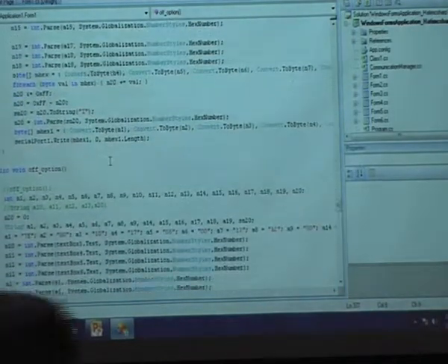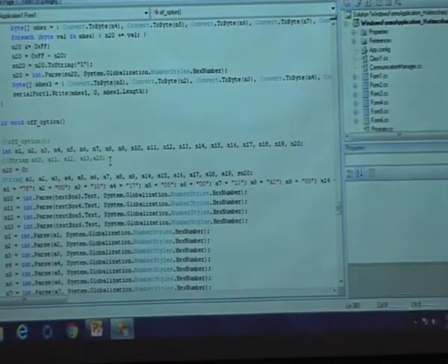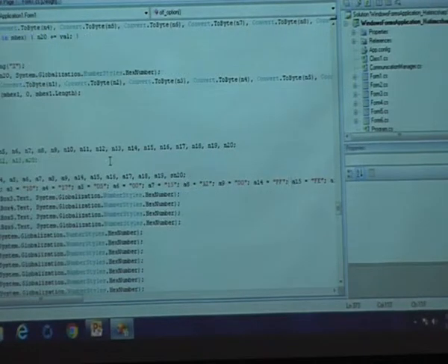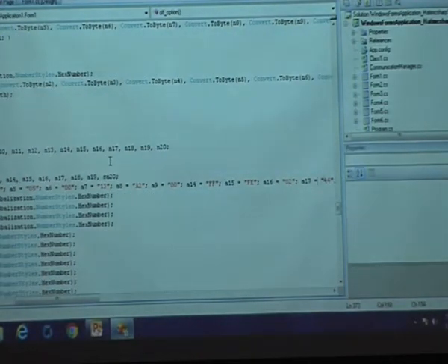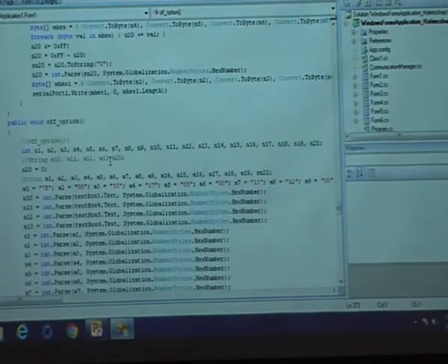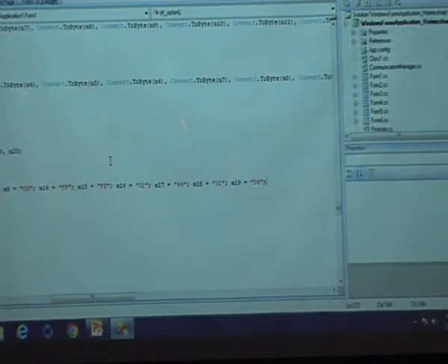Instead of making it as on, you are making that particular option as off. Select the frame, means create the frame 7E 00 10 17 05 00 13 A2 00, followed by, at the end, if you want to make it off, the value should be set as 04. The last value you are making it as 04.